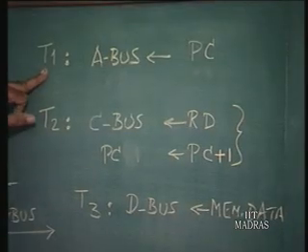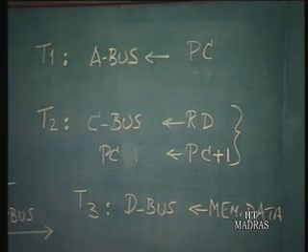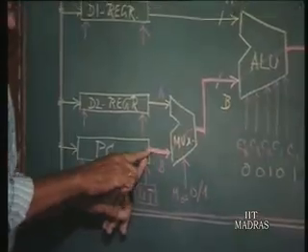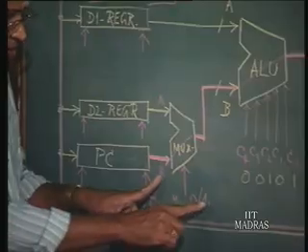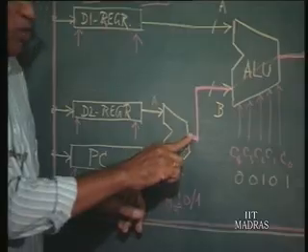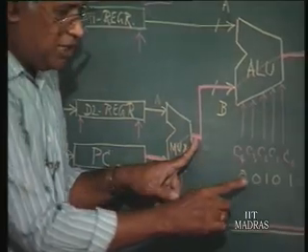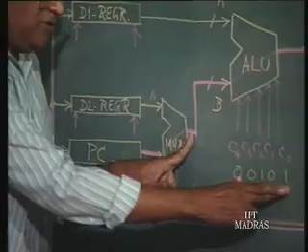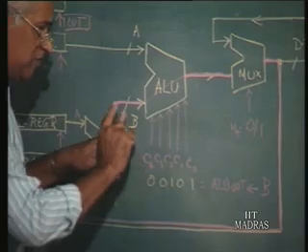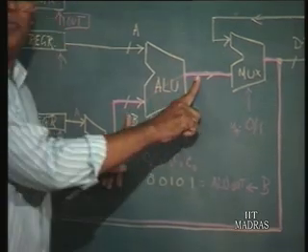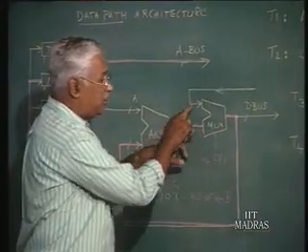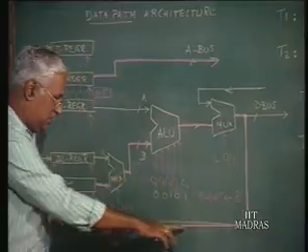That's the register transfer activity, which means generating the PC out signal, setting M0 to 1 so that this B information can go on to the output, and generating a code, whatever the code may be, doesn't matter, for implementing the function of passing the B input onto the output, and enabling this mux so that this information and not this is passed on to this.